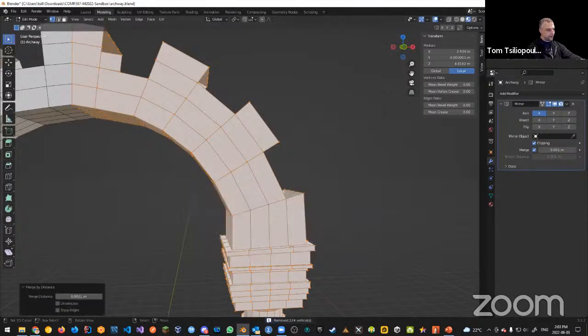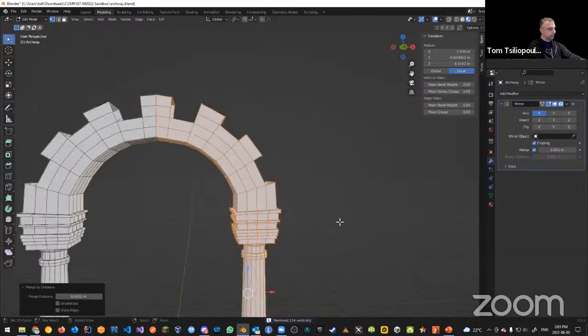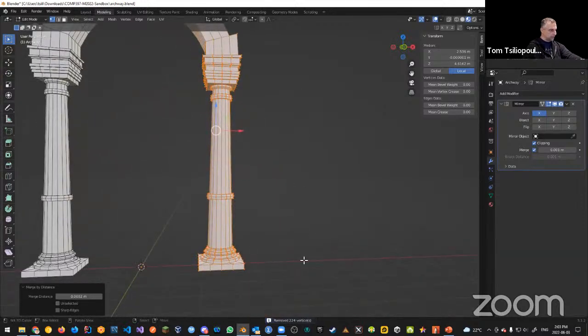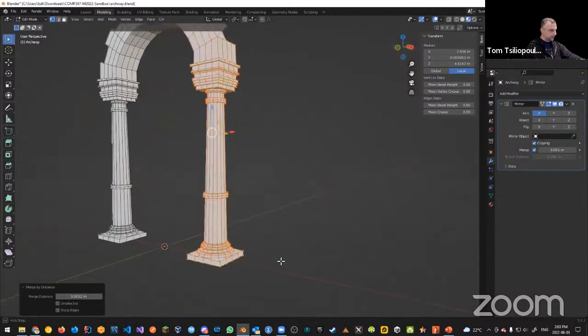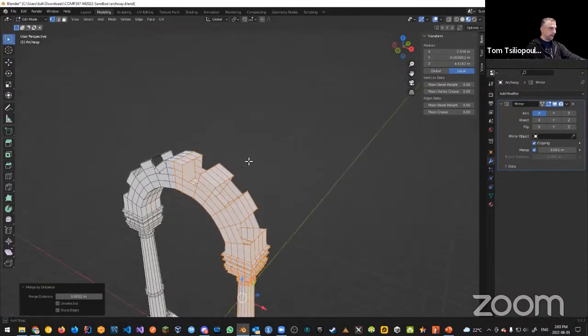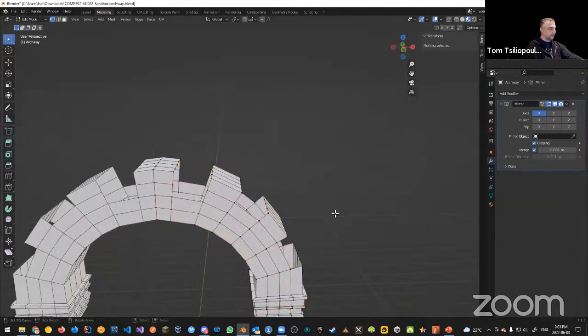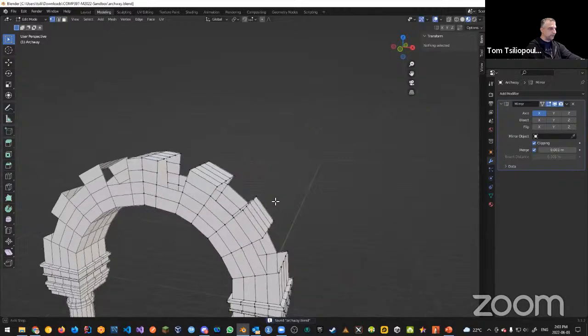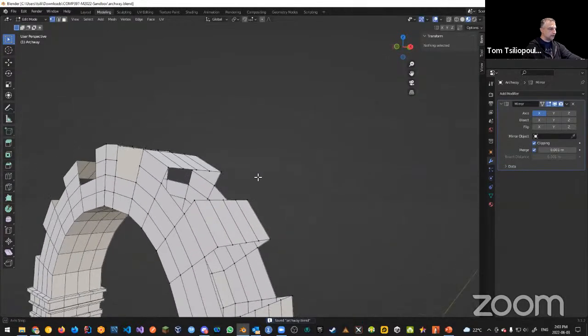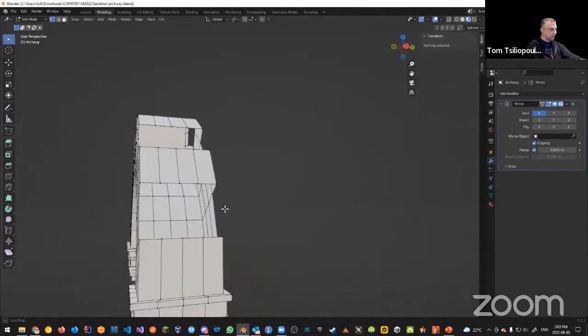And it shows me that I've removed 224 verts. This is good. Let's even move it out a little bit more instead of 0.01. Let's just make sure and go to 0.02 and then get rid of, for sure, these vertices. So any duplicate vertices are gone, okay? And you want to do this before you fix these top parts, okay? Save. So now we've deleted the duplicate geometry, hopefully. And now we can kind of work with the new geometry that we have in here.